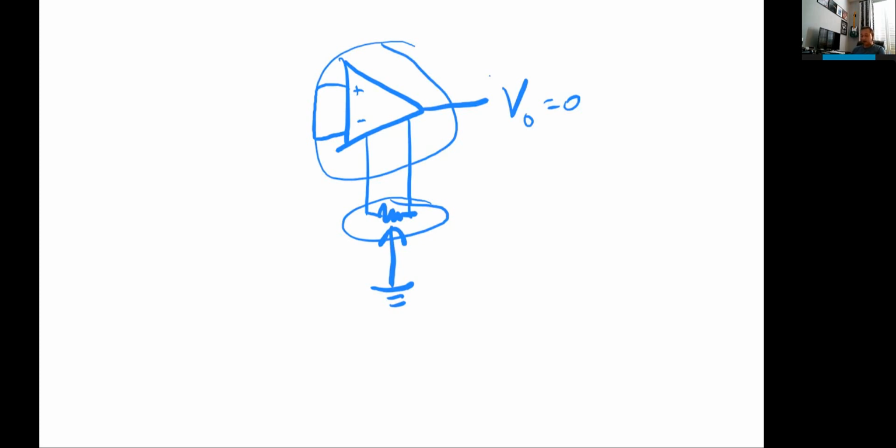Let's now take a look at another quantity that contributes to the offset. And again, all the data sheets are going to have the offset, always worst case. The manufacturer is always going to quote worst case, and is going to guarantee that it's not going to be larger than that, because this is a quantity that you want to have as small as possible.